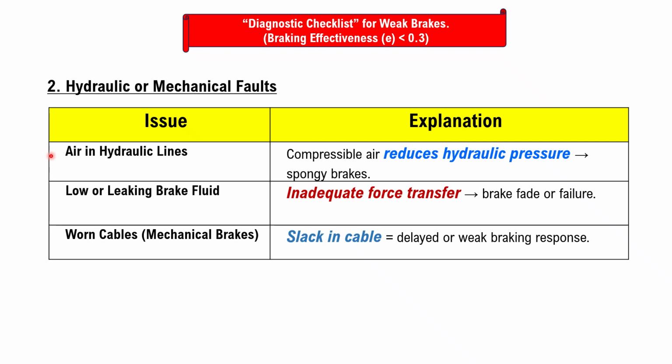Low or leaking brake fluids, responsible for inadequate force transfer, resulting in brake fade or failure. Worn out cables in case of mechanical brakes results in slack in cable, thus resulting in delayed or weak braking response.